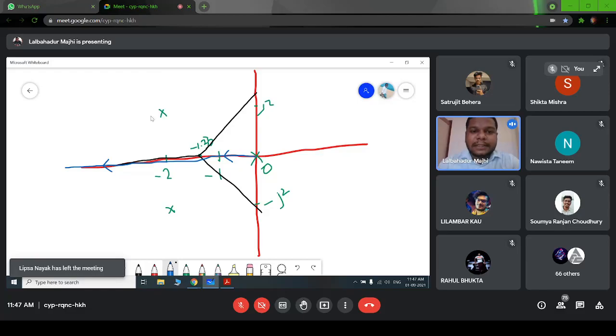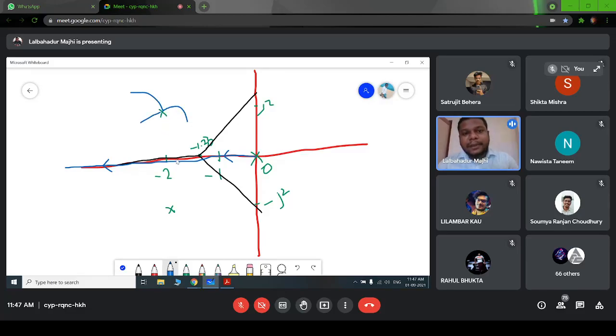So then next, from these two complex poles also, there will be a root locus branch, right? So how can we check at which angle the root locus will start? The root locus may originate like this, it may originate like this, or this, or this, right? So for this, we have to find the angle of departure, so that we can say the root locus will start or depart from that angle. So how can we measure the angle of departure?